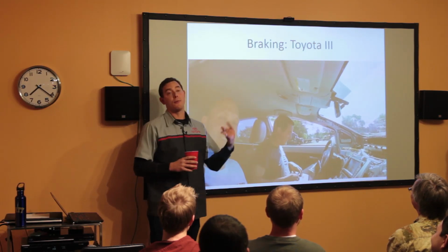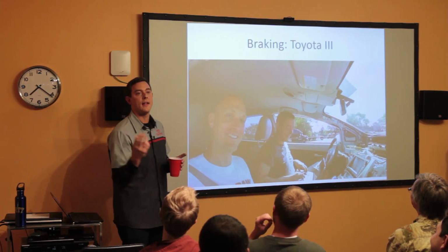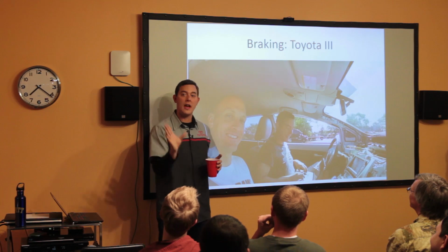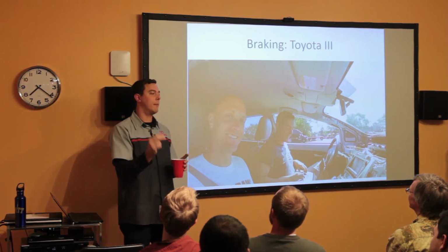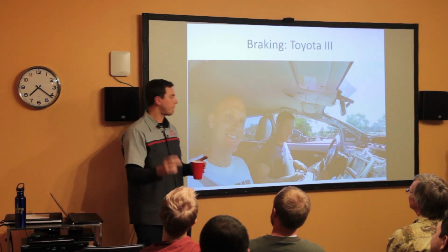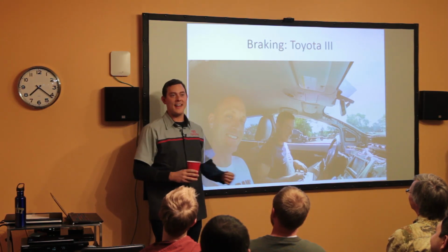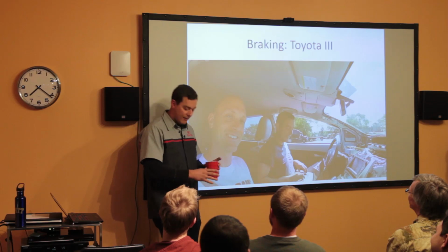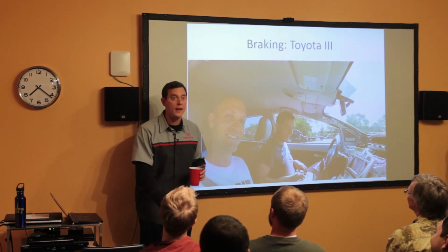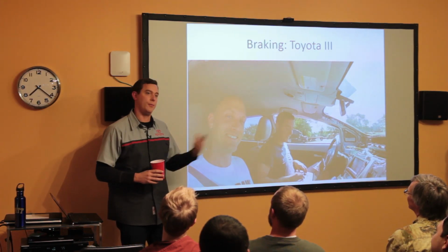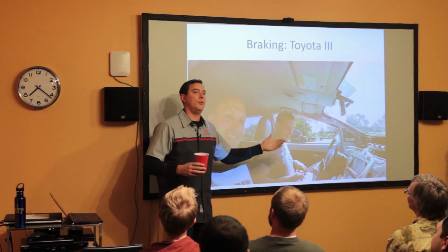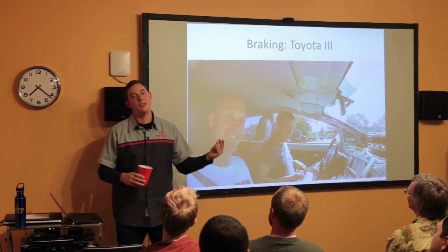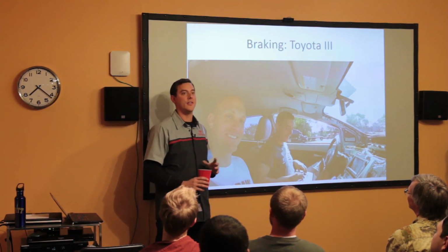And at least for the Prius, when you're stopping, it's kind of a pressure amount, right? Because they want to slow you down. They're not going to clamp them. They're going to slowly clamp. So what I did is just do 100%. The Prius has that booming 1.4 four-banger in it. So even if you pressed the acceleration pedal the whole way down and the gasoline engine on, the car wouldn't move, right? Because the brakes were clamped and it couldn't move. So this not only brakes the car, but completely immobilizes it as long as you play this message on the network.